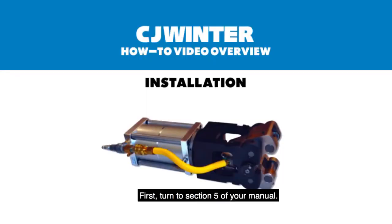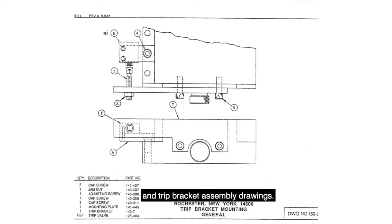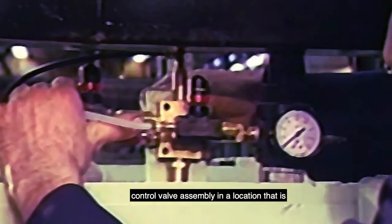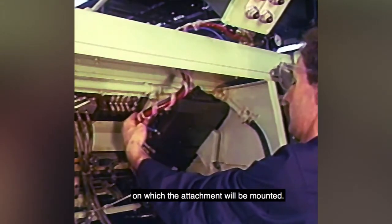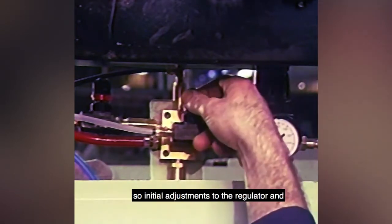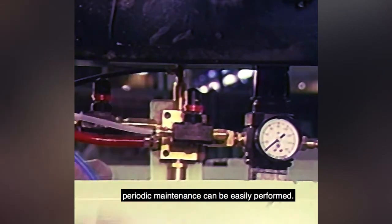First, turn to Section 5 of your manual. Locate the mounting information and trip bracket assembly drawings. Double-check that you have all the required parts for installation. Begin installation by mounting the control valve assembly in a location that is easily accessible on the machine frame. Make sure the air hoses can reach the cross slide on which the attachment will be mounted. This mounting position should provide convenient access so initial adjustments to the regulator and periodic maintenance can be easily performed.